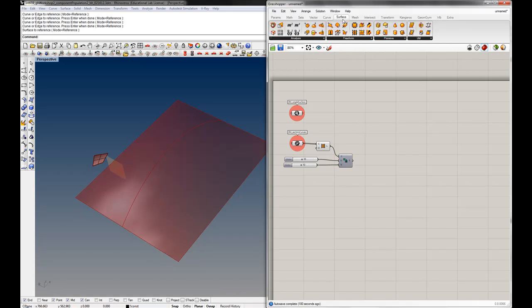And to actually get the subsurfaces, we'll go into Surface, Utilities, Isotrim. Again, that was the Isotrim tool out of the Utilities section. The surface we're subdividing is our lofted surface, and it's asking us for a domain subset, and those are our divided domains.